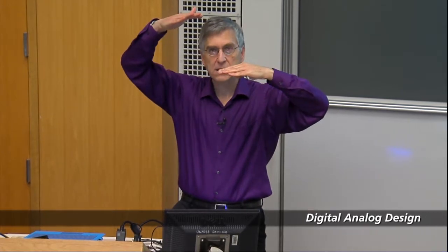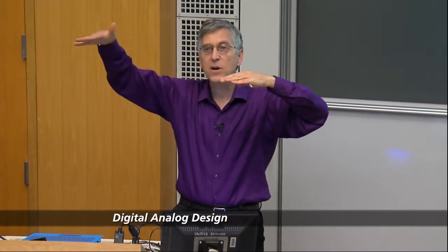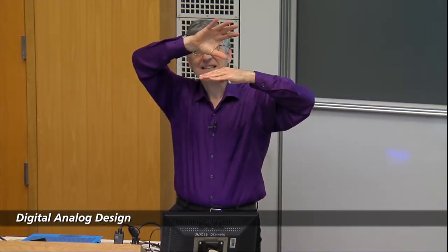And so what I always do is you make the control loop and the signal bandwidth discrete. And you think about what happens when the signal goes through in a quasi-static sense. And then you look at what the control loop does. And that's how you design the system. So you break it into two quasi-linear systems. And that's the way you think about it.